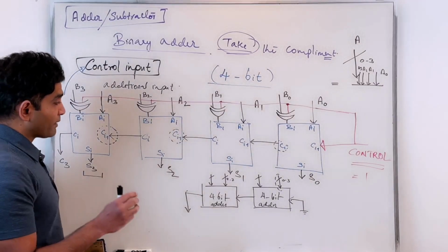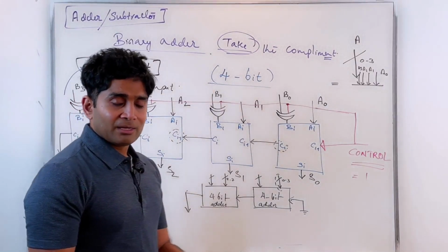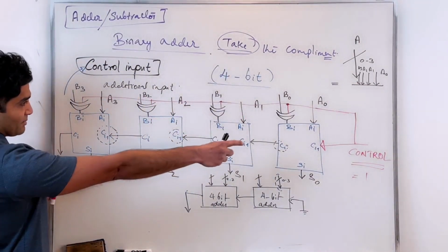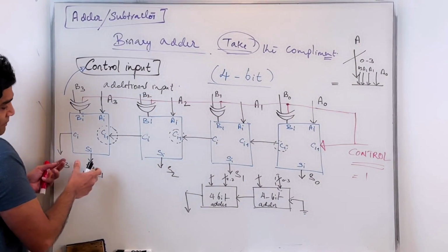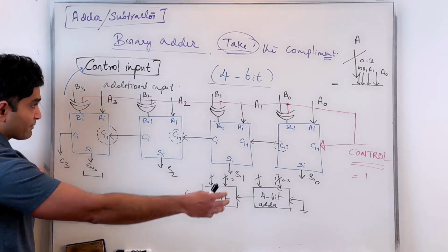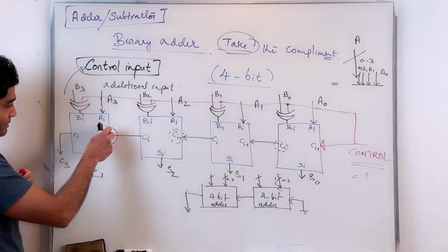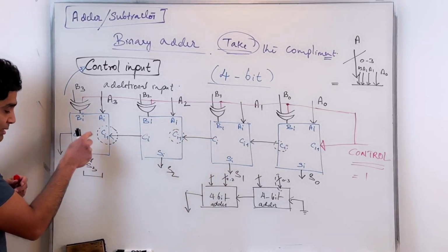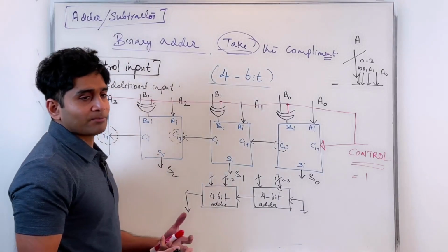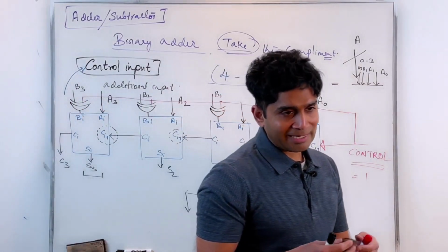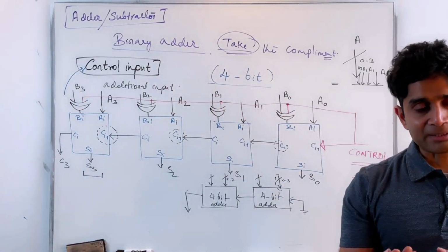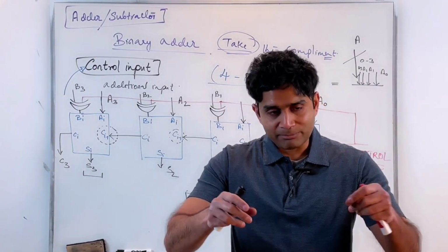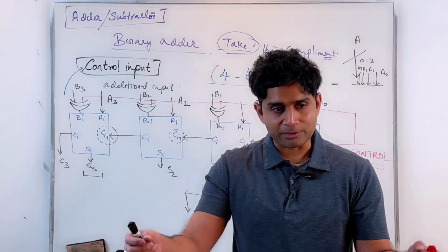Although if I wait long enough, eventually my sum will settle down. I may be getting some sums as these computations happen, but if I wait long enough, after I make sure that the right carry in is propagated through all the stages, then I will get the right sum. So my sum will not be the right sum immediately, but I have to wait some amount of time before my sum settles down into a steady value.